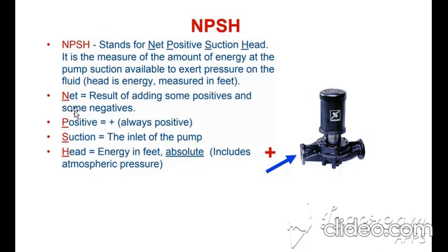In these terms, net means a result of adding some positives and some negatives. Positive means always positive, suction means the inlet of the pump, and head means energy in feet absolute.